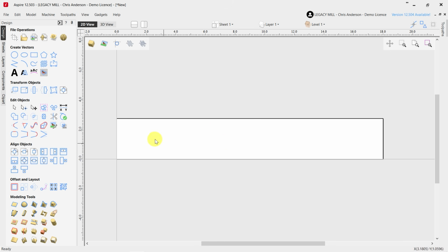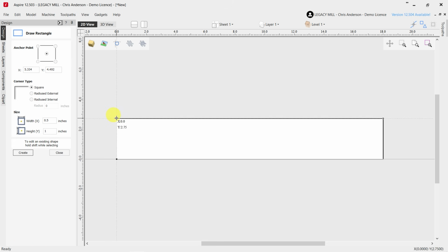Let's now quickly draw some layout of general shapes of where we want turning to take place on the spindle. Let's say that the first 4 inches of this spindle are going to be used for a square section, so we're not going to turn that section. Let's do the exact same thing on the opposite side, so we'll put another 4-inch square section here. And now we're going to draw a section in the middle between those that will be turned round. This section here, we're going to make a little bit smaller. Instead of just 2 3/4, let's make it 2.5 inches in diameter.